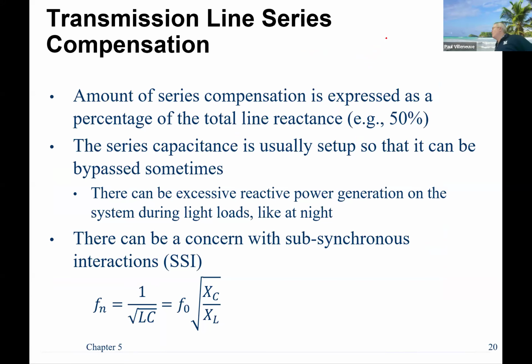Be careful though, when you have series compensation, because of the concept of resonance or resonant frequency, which is basically the magnetic energy and the electric field energy will ping pong back and forth. And you can just share energy back and forth where you can get some pretty high voltages and oscillations on your system. So that's why you have to be very careful about making sure your system is tuned, because 60 hertz is just a communications signal, right? It's big power communications, but it's still a thing. So you have to be very, very careful about just throwing things on there willy-nilly. There's things to consider.